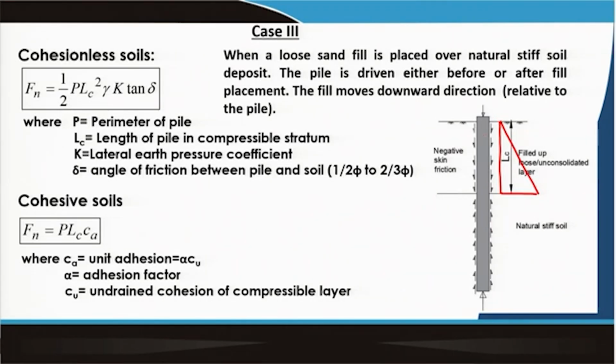But if there is a water table, as I mentioned, then you have to modify this equation or this diagram. Sometimes, if clay soil is placed and the undrained properties are given, then in a few cases, even for the first case, you should use the drained properties, because that is the actual condition, but sometimes you will find that you only have the undrained properties.